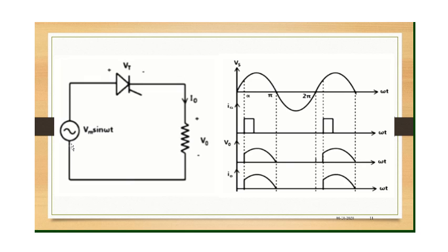At the input, you have the AC supply. Vs is your AC supply, all right? And this is your SCR. And remember, the gate drive circuit is not shown here, but it will be there because you have to use it to trigger or give the gate signal, right? So Ig is my gate current that will be applied here at the gate terminal, okay? And we know that whenever the gate signal is applied, only then the SCR will turn on. When the SCR turns on, then there is a flow of current in this circuit. The circuit is complete only then, isn't it?